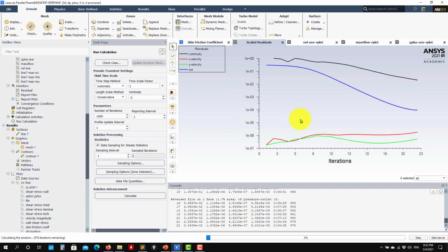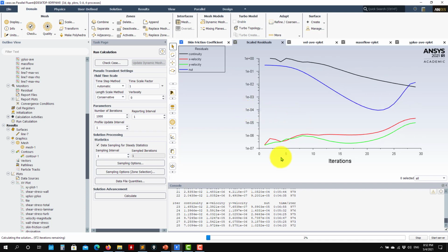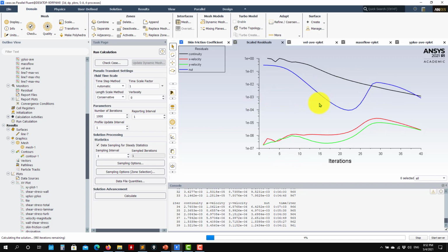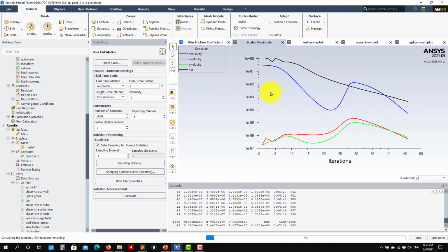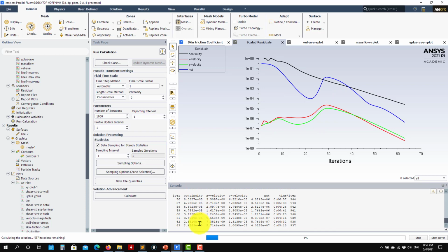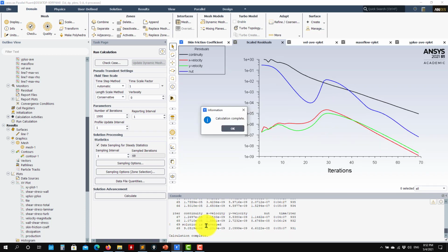And off you go, the solver. So probably this should be much faster because you have less equations to solve. Let's see what happened, but see that we have a very good convergence rate. Okay, so it should arrive soon. So here we are already there, and voila, we are there. So see that as you compare with the K omega, this one was much faster.